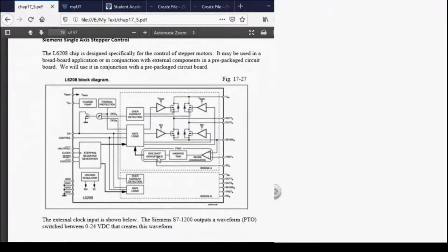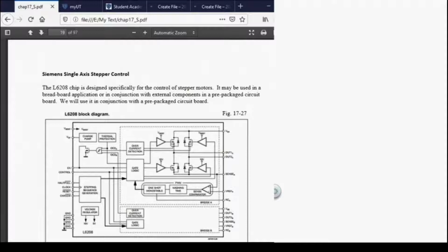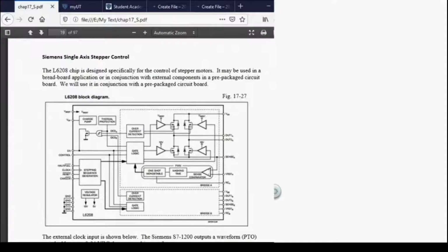So we're asking you to do something a little bit different from that, but on the other hand, that's the starting point. Now, with the stepper controller, we have tried various things, and at the beginning, when we first bought the earlier version of the Allen Bradley and the Siemens processor, I knew that the Siemens processor, because I'd gone to a little school on it, could handle what you'd call a stepper output, a pulsed output, PTO, pulse timed output, that would basically give you the ability to control the number of pulses, which gave you the speed, and if you pulsed, it meant you moved a certain angle of the shaft.